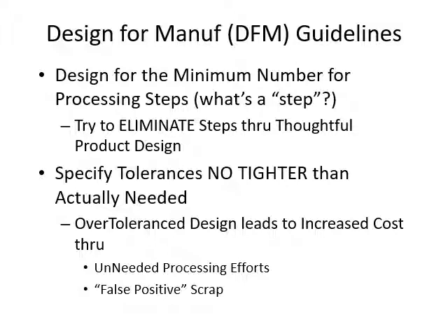Specify tolerance no tighter than actually needed. So some tolerances can be loose, and some tolerances need to be as tight as possible. Over-tolerance design leads to increased costs through unneeded processing efforts and false positive scraps.